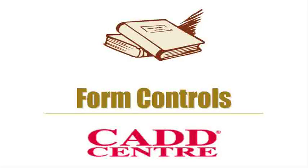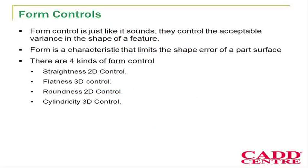We will discuss these 14 symbols one by one. First, let us discuss the form controls. As mentioned, form control controls the shape of the feature. There are totally 4 kinds of form control: straightness, flatness, roundness and cylindricity. In this, straightness and roundness are 2D controls, whereas flatness and cylindricity are 3D controls.